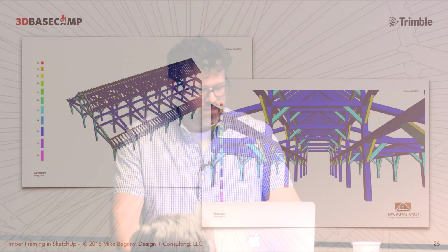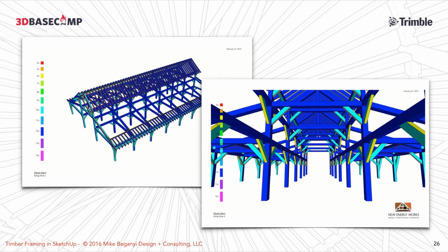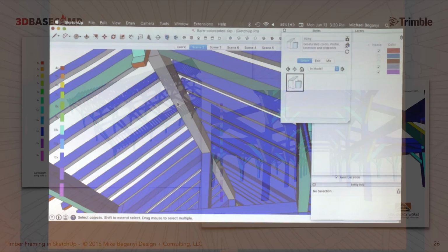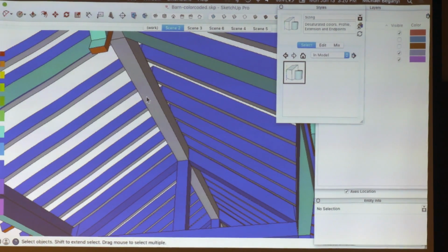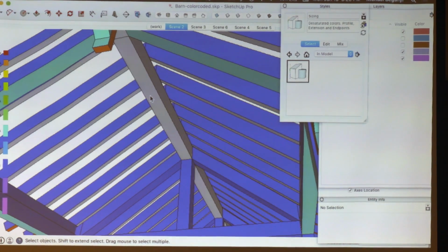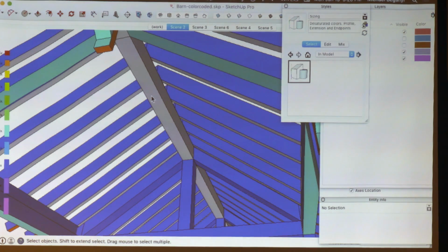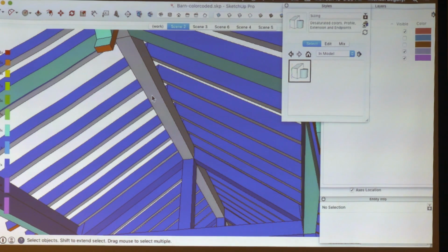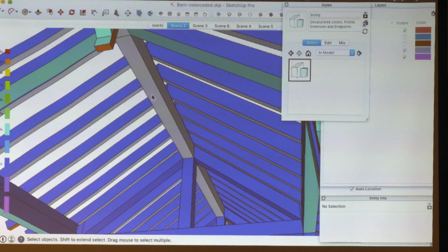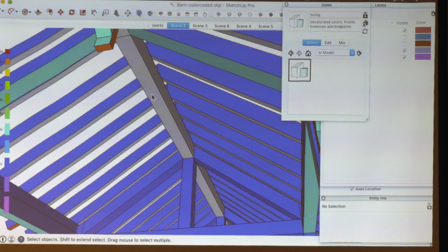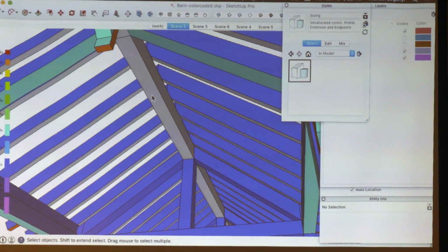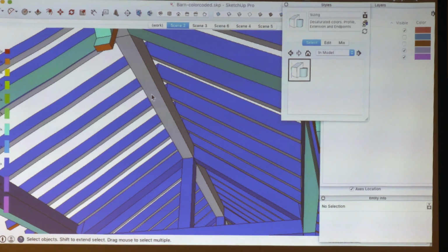Once in a while, the plugin, like everything in SketchUp, will choke, and you'll see that it put these as gray. So it either means that A, the timber isn't in compliance, so it's not 7.488888 to 8.0001 for an 8x face. It came out screwy. Either I built the component wrong, or maybe I accidentally push-pulled it. So I'll double check that timber to make sure it's the right size. And then if it is correct, I'll just go in and manually paint those faces before I send the file out.